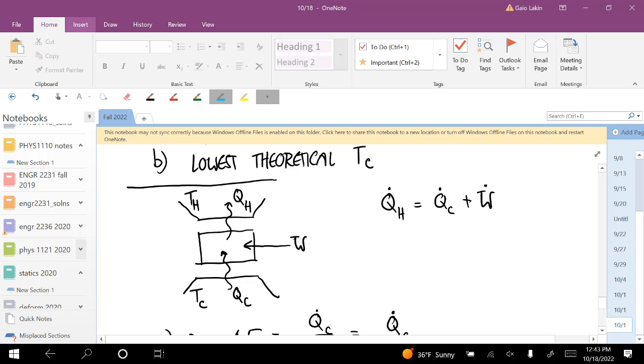Putting it in thermal contact with the cold region, like the inside of the refrigerator, getting the energy to flow into that gas. Now, as you hold it down, you run to the other room, the hot place, and you let the piston rise, the temperature goes down, put it in thermal contact with the room, and that energy is ejected into the room. And now you run back to the inside of the refrigerator, push it down. So that's the principle of how a refrigeration system works.